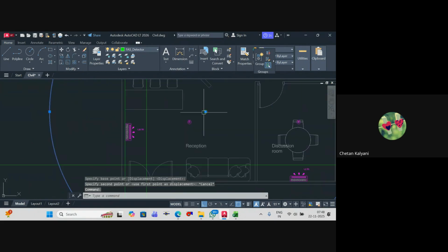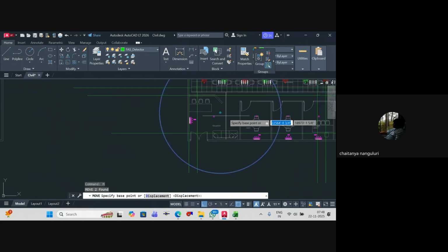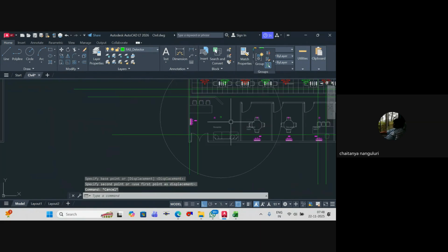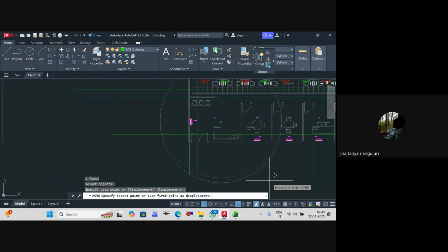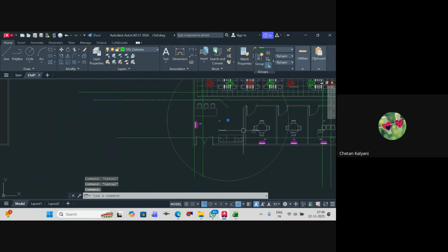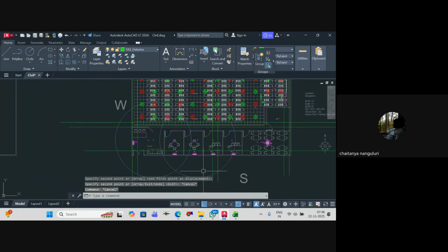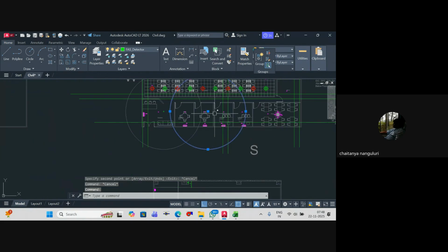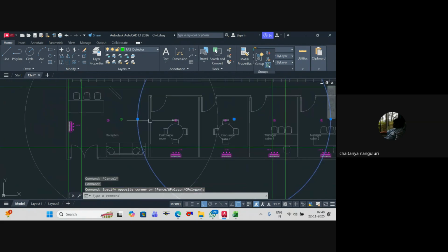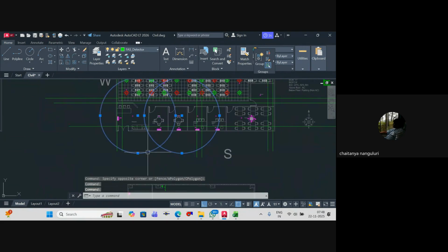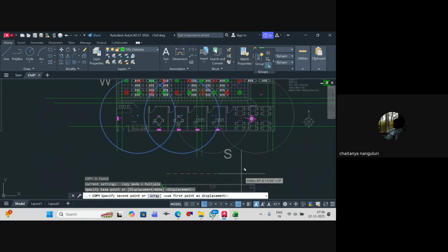Sorry. Anywhere I can place it, there's nothing wrong, because the entire zone is a single thing for me. If you place it there also, I'll not be able to cover. So in this entire zone, I require two numbers. Above we require one, and here also we'll place one. Similarly, in this zone also, two detectors are required. Two detectors, we'll place over here.